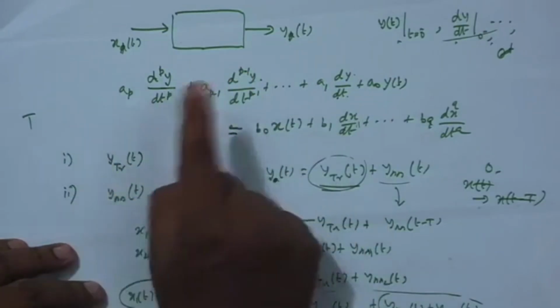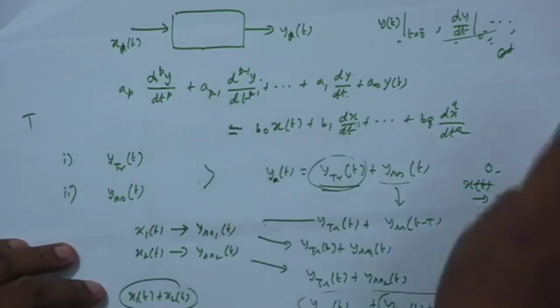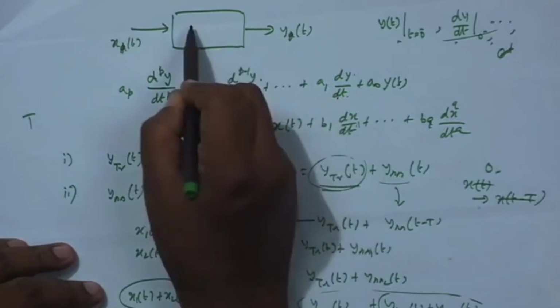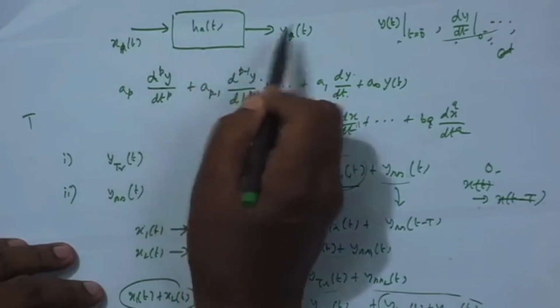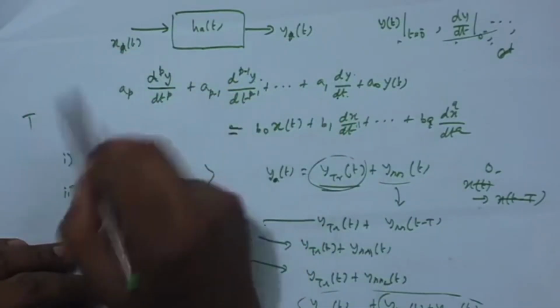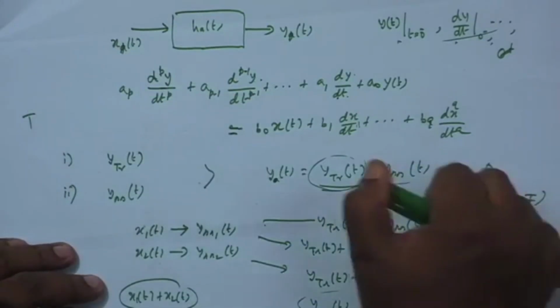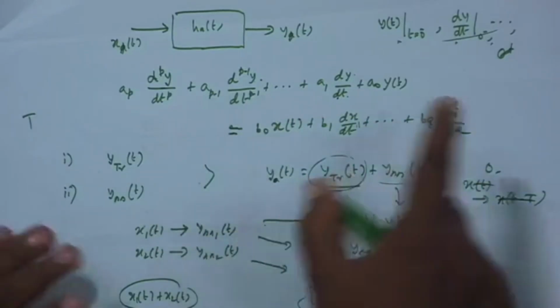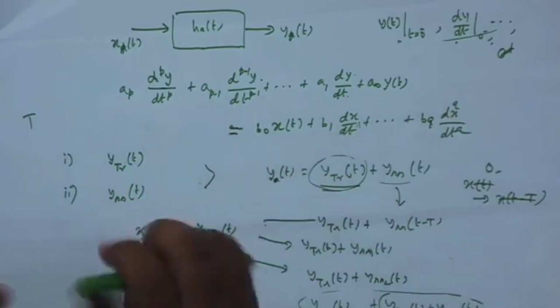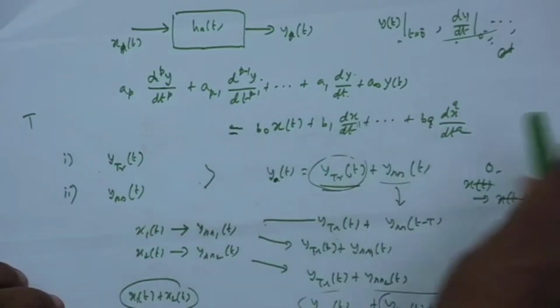So, it will be a linear and time invariant system. Therefore, if you give a delta at the input and record the output and call it the impulse response, then another way of obtaining the output will be convolution between these two. In this case, the system is linear and time invariant because there is no transient solution; initial conditions are 0. Under this case, if I apply the Laplace transform to the left hand side and right hand side, what will we have?